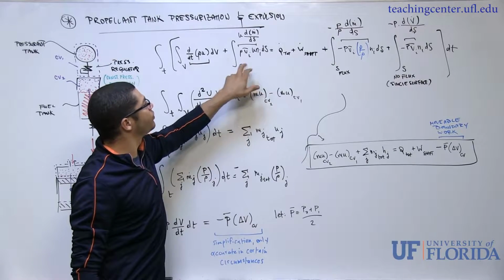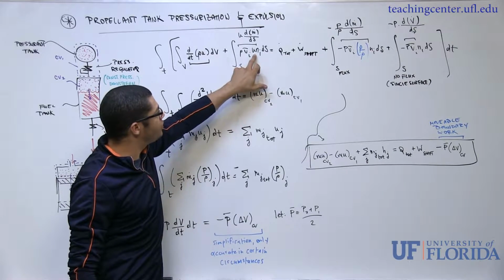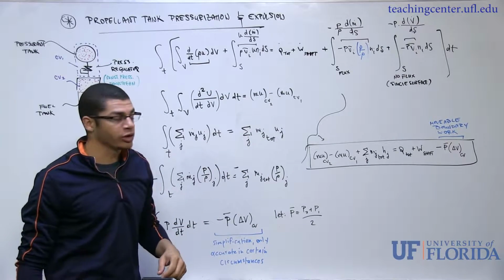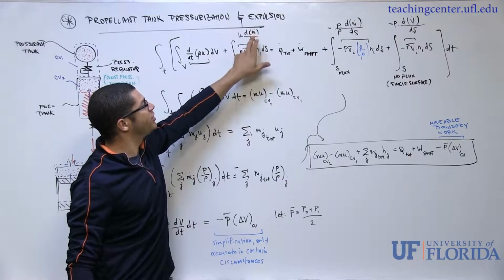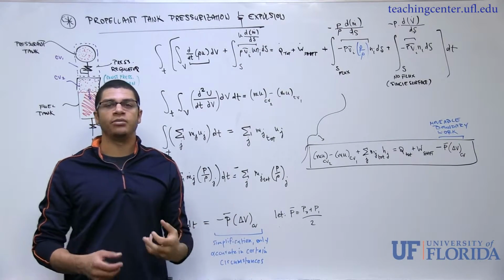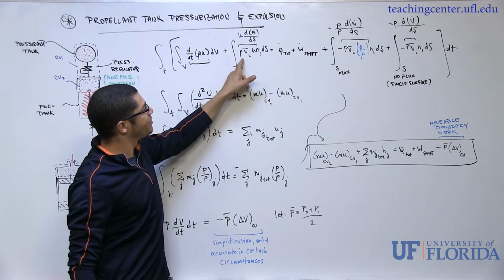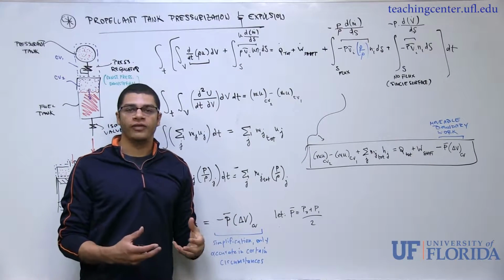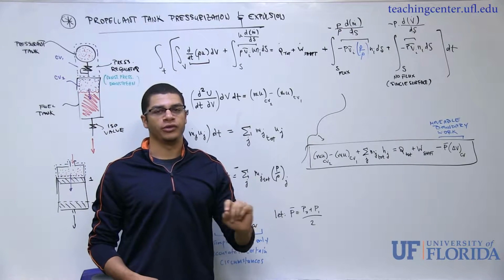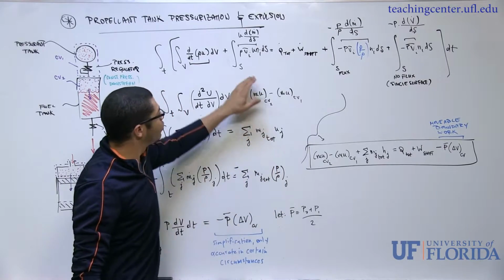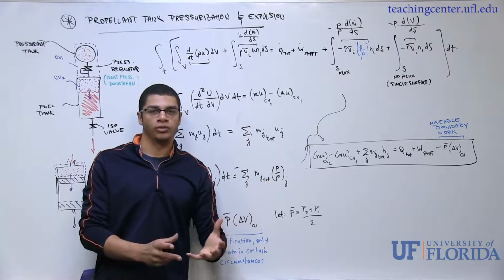So again, density, the average velocity, or the velocity of the fluid at that point, and then the specific internal energy. The product of these three is just going to give me the specific internal energy times this expression here. So I've got dm dot ds. And really all this is saying is that rho v itself can be thought of as a differential amount of mass flow per unit surface area. So a differential mass flux.